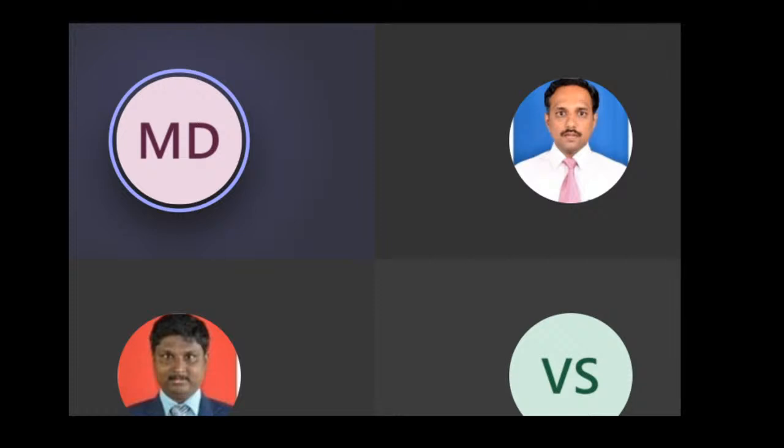It will build the heat map. But once the printing is done, what happens to each of these layers? So during printing, you can map it, but post printing, it is going to be a serious challenge. One way is the simulation packages. Second, experimentally, you can destructively go for micro drilling and put the probes and sensors and measure it. That is possible. I hope I answered.